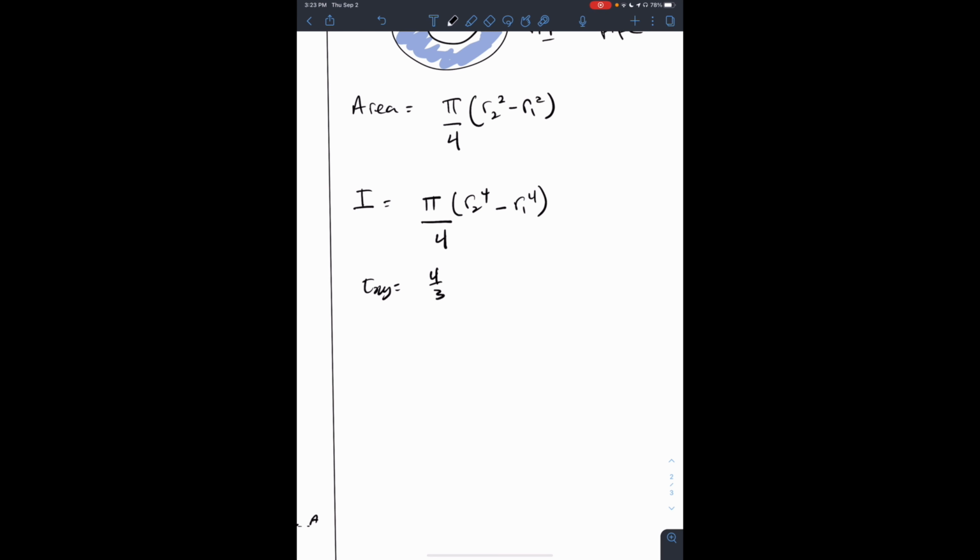We write down all our stresses. We have tau xy, again I'll just put back in everything here, V on A, I'll say V max. Our sigma bending is really our sigma x, because you could recall the bending stress acts in the x direction. If you were to bend a beam or bend a ruler, for example, what you're really doing is stretching the top surface and compressing the bottom surface.